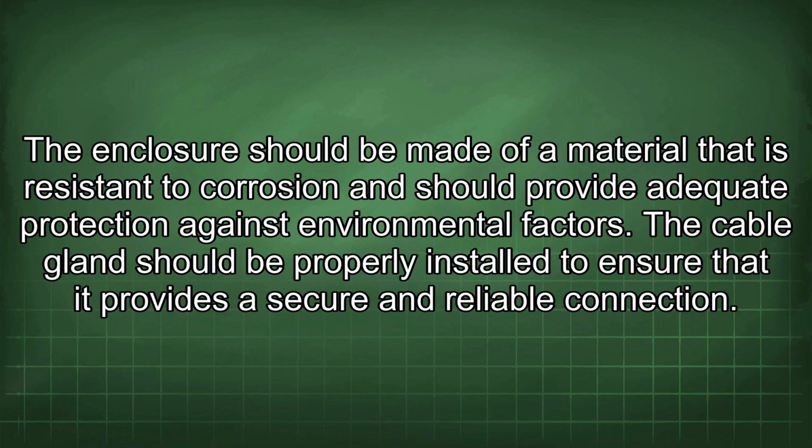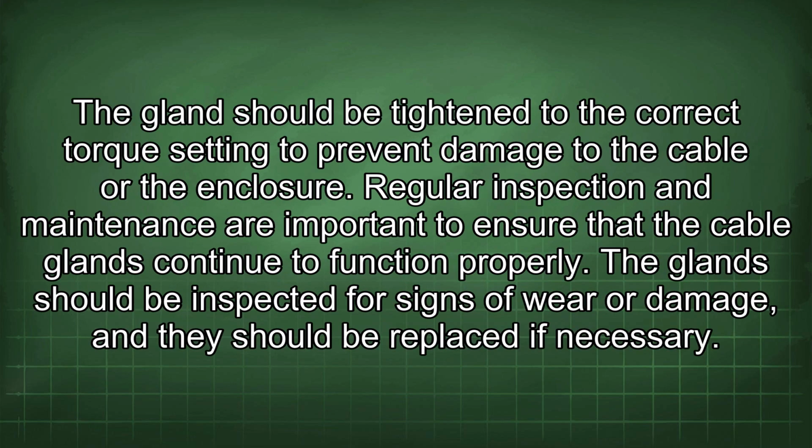The enclosure should be made of a material that is resistant to corrosion and should provide adequate protection against environmental factors. The cable gland should be properly installed to ensure that it provides a secure and reliable connection. The gland should be tightened to the correct torque setting to prevent damage to the cable or the enclosure.